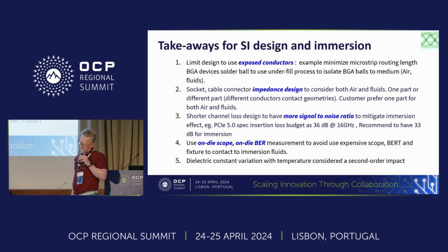And also using on-chip methods to avoid having to fix things later in the design process is also going to improve your chances. Finally, a consideration that we're looking at the moment, and it's a little bit unclear, but we're working on this, is that in some cases the dielectric properties will vary with temperature, but also the quality of the contact between the connector bodies also varies with temperature due to expansion of materials. So there is a thermal effect, which is secondary.